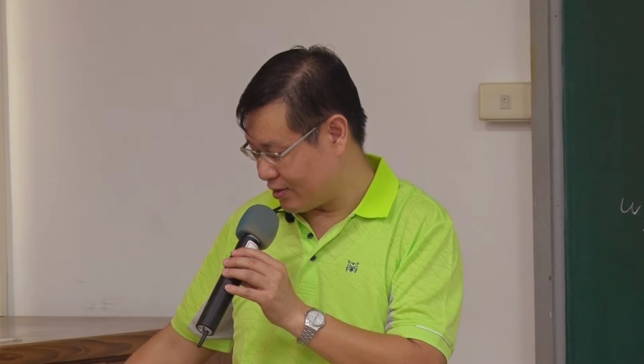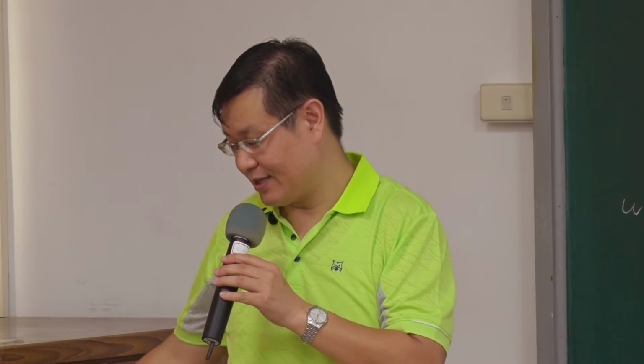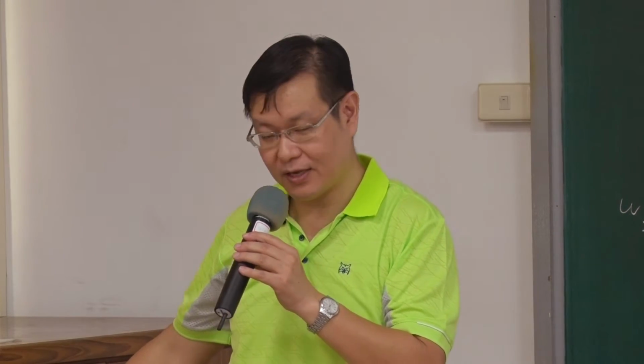Yeah. And also for diffusion, you can put it there for a very long time. You can end up getting a lot of amount of ions. But for implantation, it's not easy, because you have too much concentrated ions in a small region. You will give a lot of defects in this region. Sometimes it will break the whole surface. So there's one method by using this implantation to break up a small portion of the silicon substrate. For example, 1 micron silicon substrate from the surface, separate from the surface, by using this method. Okay. So it's not easy to implant too many ions.